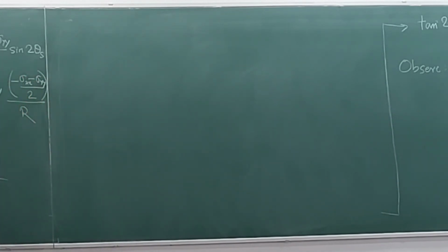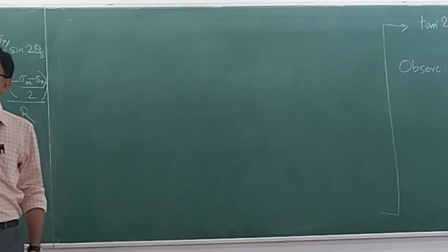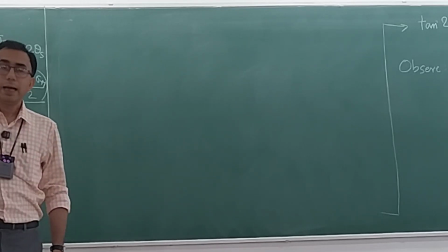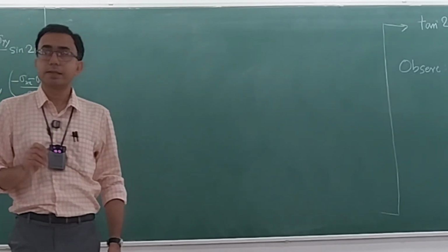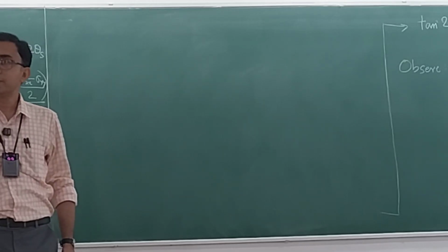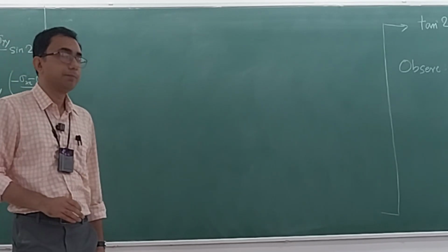See, all of these is under the purview of the plane stress condition which we had described earlier. Now, in plane stress, what do you have? You have, in general, non-zero values of sigma xx, tau xy, as well as sigma yy. They can be zeros, but in general, they are non-zeros. But what you require via the application of the plane stress condition is that sigma zz should be 0, tau zx equal to tau xz should be 0, and tau yz equal to tau zy equal to 0. This we have already mentioned earlier.